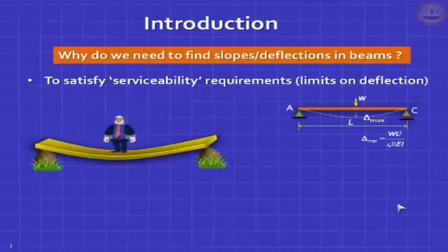So if you model this gentleman standing on that bank, you would model it like this: a simply supported beam subject to a point load in the middle W, and we have a formula there, WL cubed by 48 EI. We can prove that, and we will prove that in today's session. We need to know it and to ensure that that deflection is within acceptable limits.